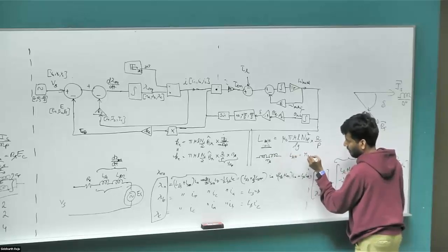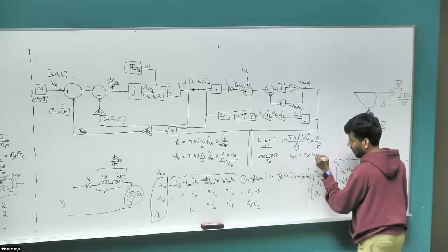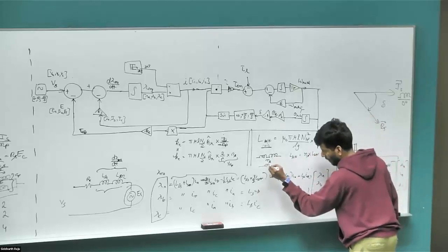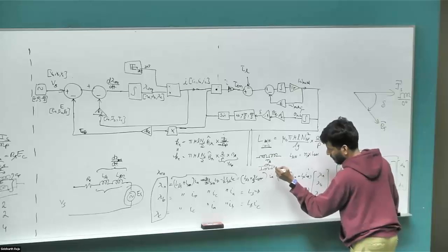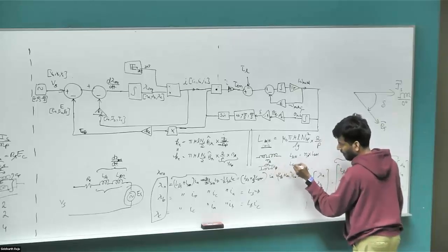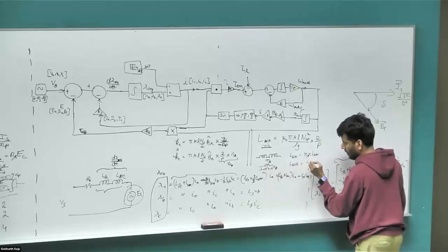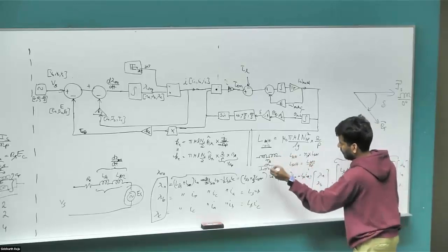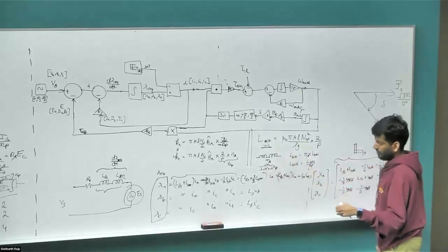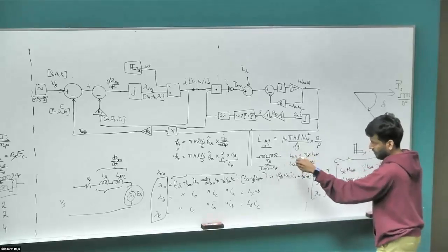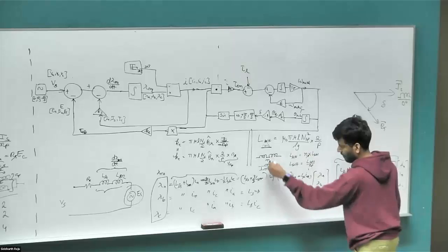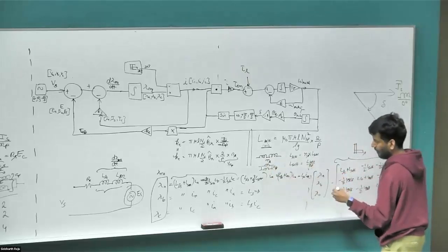So it is going to be NS times L self. And instead, if you have these coils in parallel, with the number of parallel pathways being NP, then L self is going to be inductance divided by NP. Think of it as parallel resistors. The net resistance would be RP, the resistance divided by the total number of parallel pathways. If the resistances are the same, the same happens with inductance.